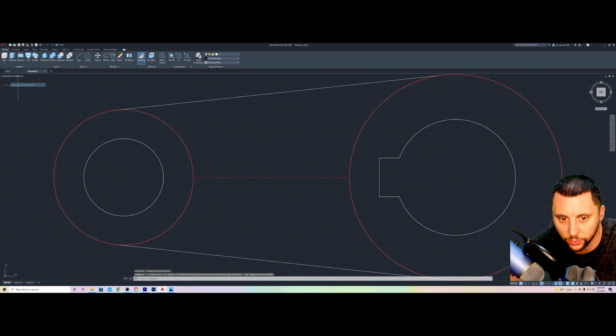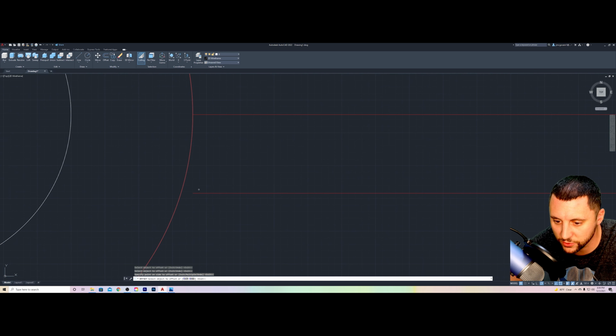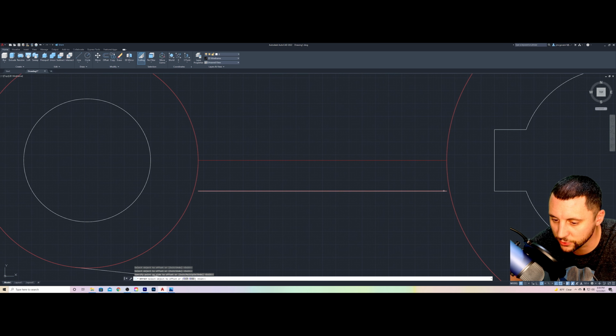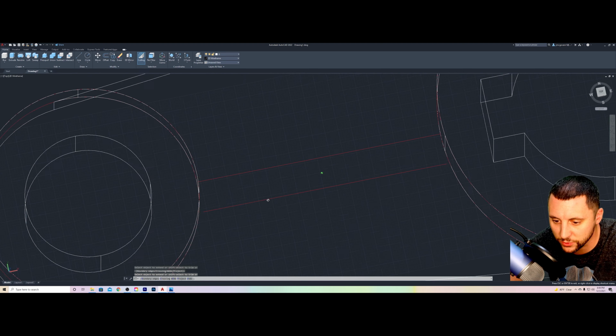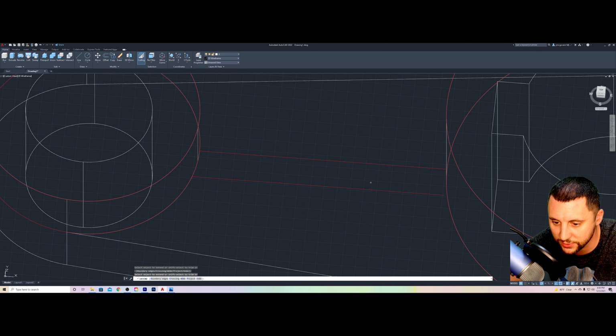From the top view, you'll see now, like I was talking about before, if I offset this 6, it's going to end up short of the circles, and it's going to end up short of that circle as well. But since I have those circles on that bottom level, I'm able to extend it to those circles, and it's still at the bottom at the flat surface. If I was floating up here up top, it would be a diagonal line in space that would get extended, which would then get extended down lower than this top surface and higher than this surface, which is kind of hard to explain, but take my word for it.